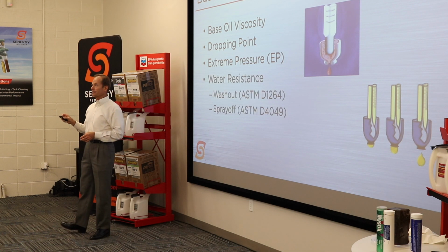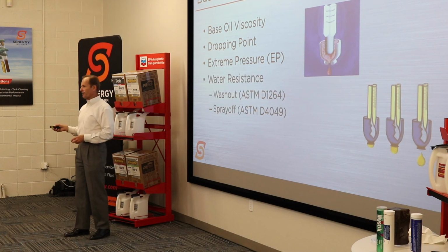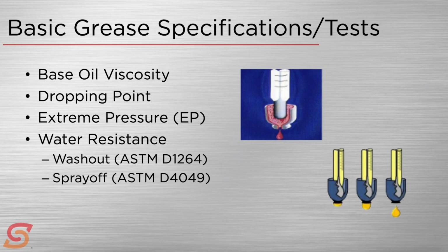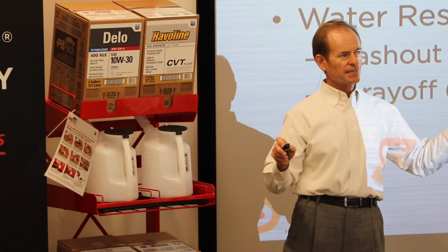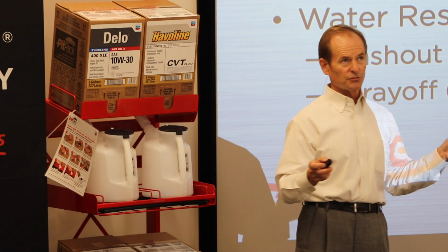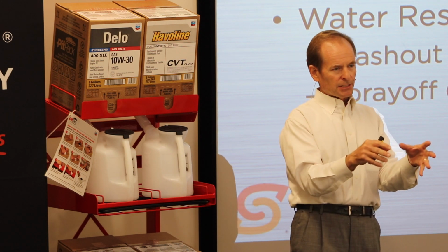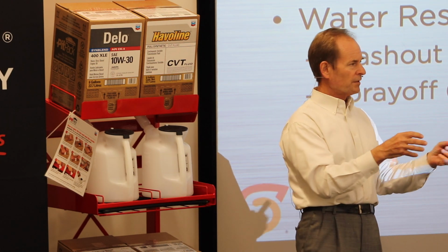Another set of tests that are worth paying attention to, and that you will see from time to time, are the water resistance tests. Okay? There are two of these: water washout and water spray off. And if you're not paying attention, you can get the two confused or be comparing one guy's washout number to one guy's spray off number. So there are two different tests, and that's why I thought I would throw them in here to help reduce some confusion. All right, the water washout test kind of simulates what's going on in a wheel bearing.